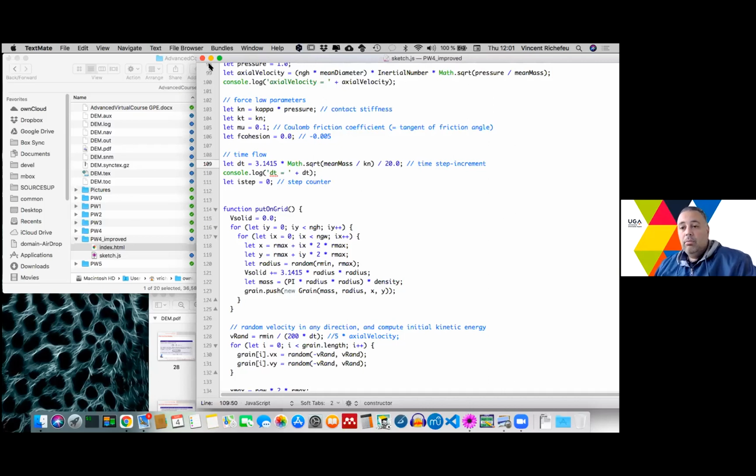This law may account for different features. For instance, volume changes. You have to set it in the law. If you want to make a cycling loading, it has to be defined in the law. Everything you have to analyze has to be defined in the constitutive law.